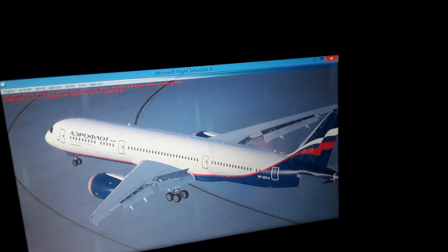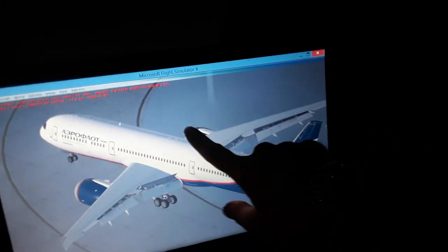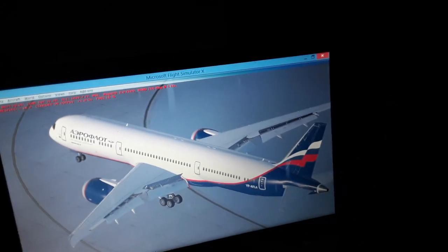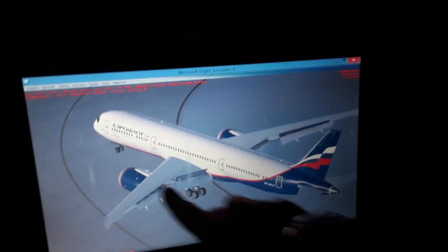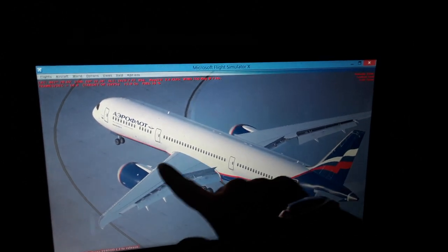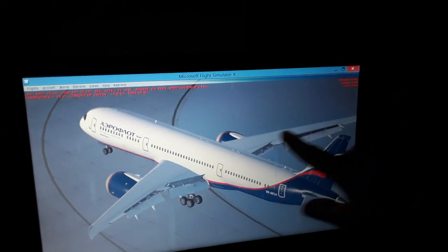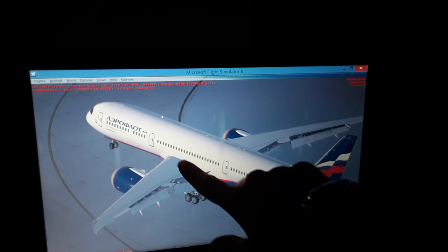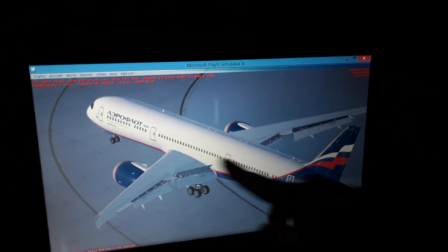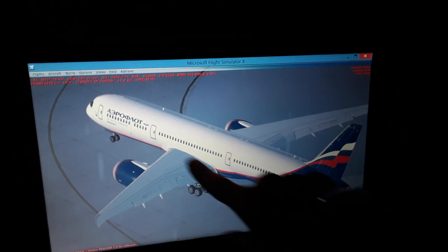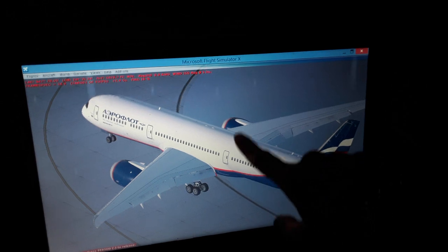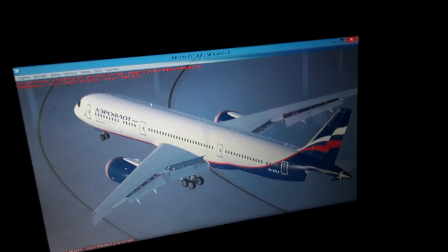So these are the vectors of the thrust from the engines. We have the mean aerodynamic chord position here, the MAC, which is where the maximum aerodynamic lift occurs in the wings. It is at 23% of the mean aerodynamic chord of this aircraft. It is where the maximum aerodynamic lift occurs in the forward wings. It is also the position where the stall will begin, where the airflow becomes detached all the way back when we fly at a given angle of attack and a changing airspeed.